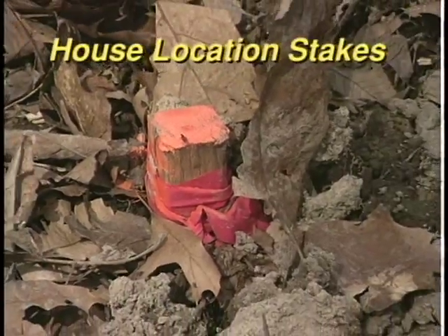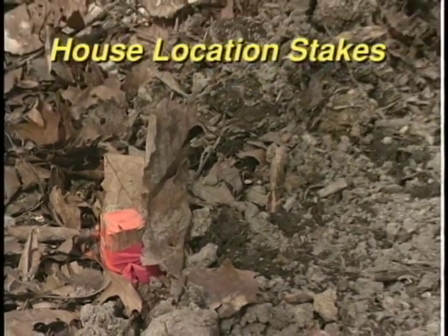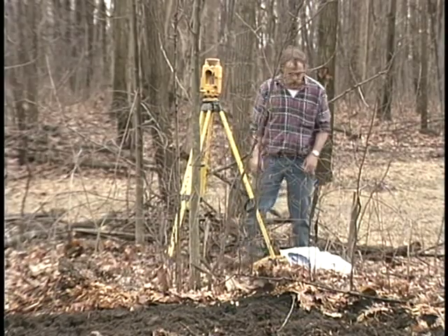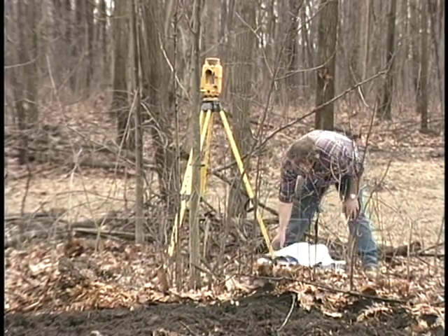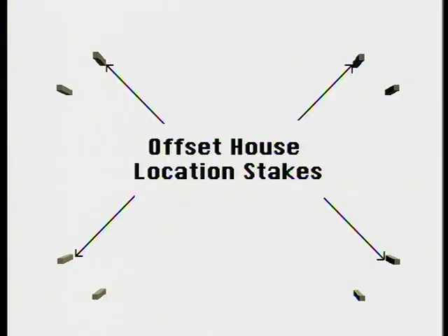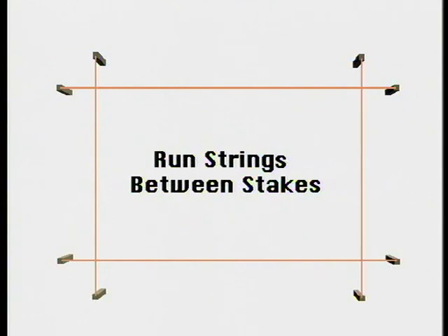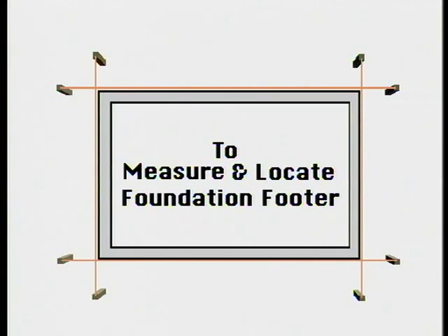Generally, to lay out the footings, use the back-set house location stakes established by the surveyor. Your plot plan will give the distance the stakes have been placed from the footer. Run nylon layout strings between these stakes for taking measurements to establish the location of the house foundation.